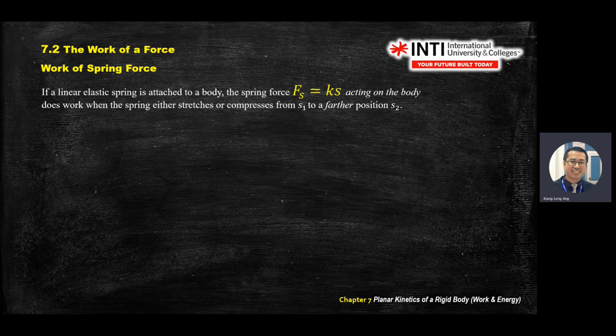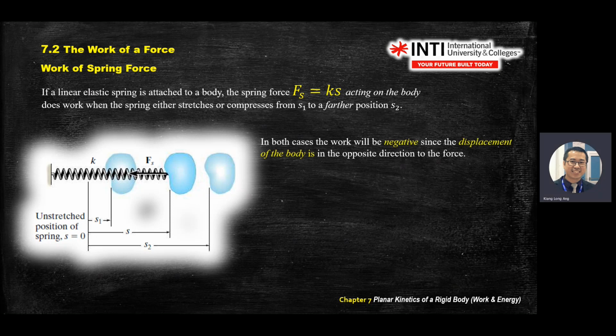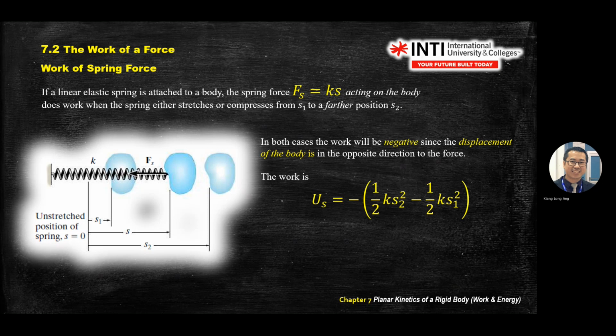Spring. You have a spring system in your final exam, just for your info. Spring force, again, we now deal with work. How does a spring create force? How do you calculate spring force? k multiplied by the distance traveled by the spring, right? Then work, you take the force multiplied by the distance traveled, right? So you actually have this one: work is half k s squared, right?